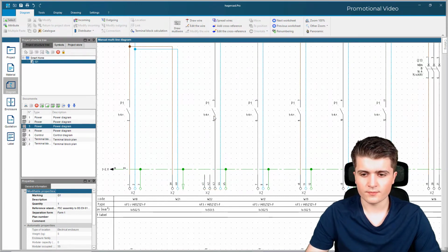which we can use. And now I simply draw a wire here from this point on and create sort of a bypass to our switching contact and move it down again here. And now in this cable we have 1 wire which is switched by our switching actuator and 1 wire which isn't switched.